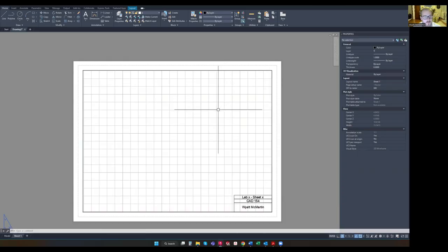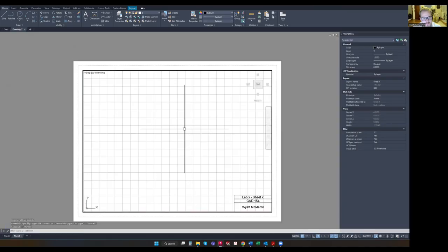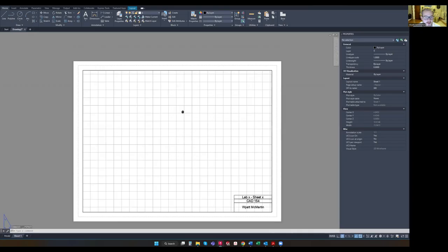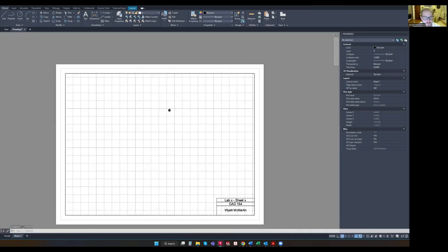So what we want to do with that, go ahead and double click inside of it. And be a little careful with this. Just double click and don't do anything, and wait until you listen to what I have to say here. So double click. It's going to make that bold. If you try to pan your screen now, holding down the middle mouse wheel, you're not going to be panning like you were before with the whole Paperspace.